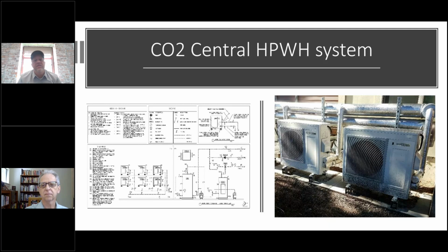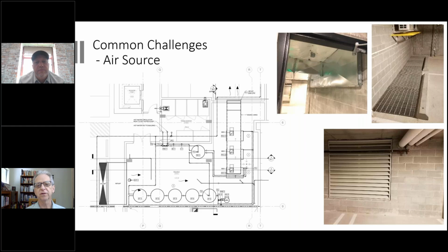But CO2 systems are some of the highest performing heat pumps that we've seen. And you'll see that in the qualified products list that NEEA manages. The CO2 tends to be the top of the list. And they work fine down to 5 degrees. So Western Washington, it pretty much handles everything. You don't need any backup heating.